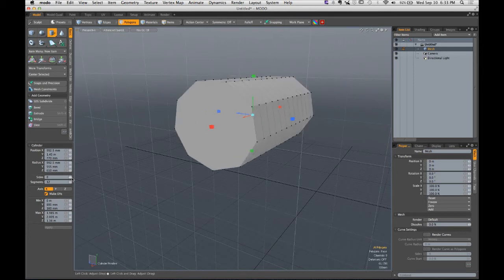All right. So the higher this value is, the closer and closer we're going to go to being a perfect circle. Now we want to keep this in check. For me personally, 24 sides is kind of the max. At times, occasionally, I'll jump into the 40s and 60s, but that is very, very rare. The more geometry we have on our models, the more polygons we have, the longer it's going to take to render. So we've got to manage this. Don't go crazy with it.